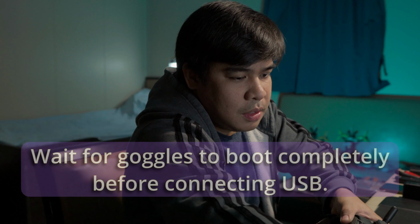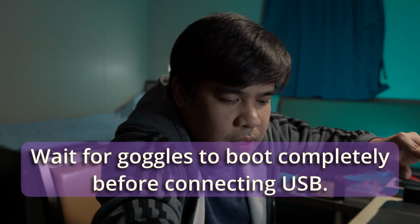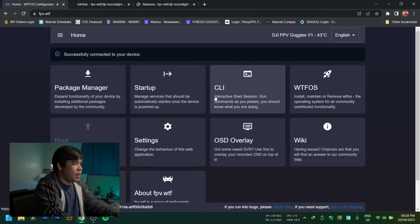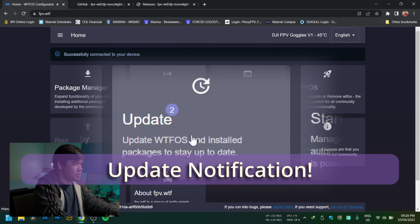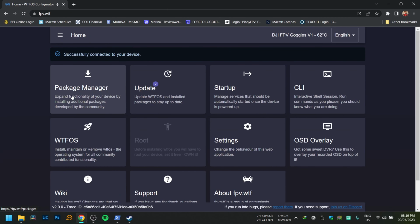So for those who haven't tried Moonlight before, you need rooted goggles, or if your goggles are already rooted, you need to update them to the latest version. Power up your goggles, connect them to your PC, and open FPV.WTF and make sure that you don't see any update notification here. That means that you have the latest version of WTFOS and the packages.